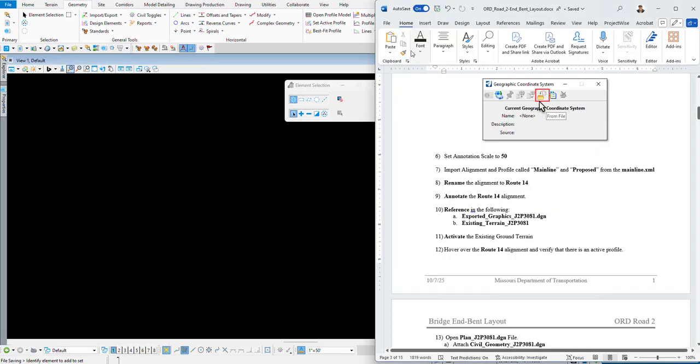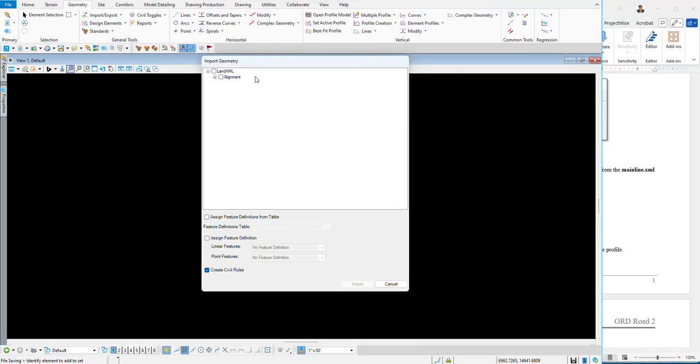And when you do, you get eventually another dialog. And here's our import geometry. Now, I always like to talk about these little plus signs. When you're bringing in geometry, I always like to use the plus sign to navigate all the way down to profiles and then work my way back up. The reason I do this, as you can see, I'm opening them up. A lot of times when you get an XML or an old GPK, you'll have multiple profiles in here, and you only want one, maybe two. This will allow you to select the one that you want. When you do that, it knows it's going to go up and select the rest of it, so we're going to bring in the correct profile that we want. This case is easy. There's only one. So it's not a big deal.